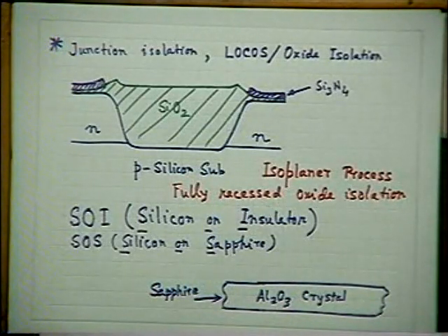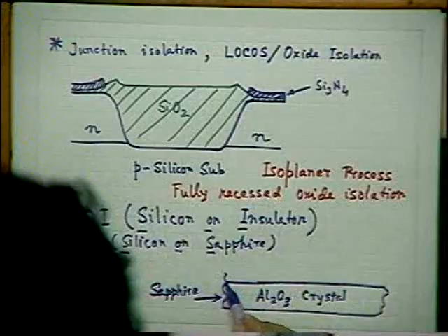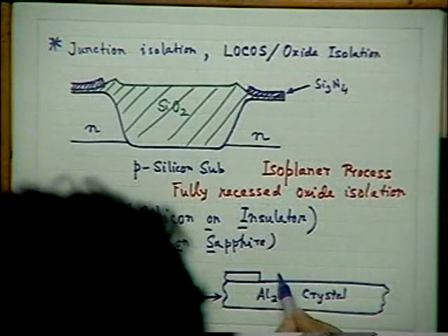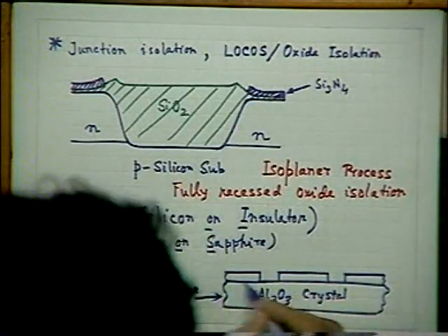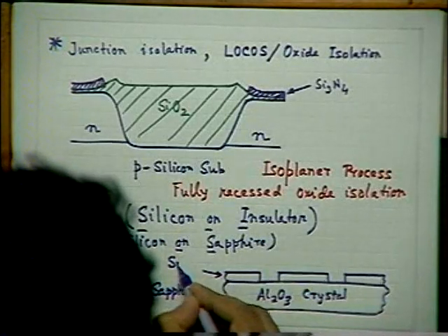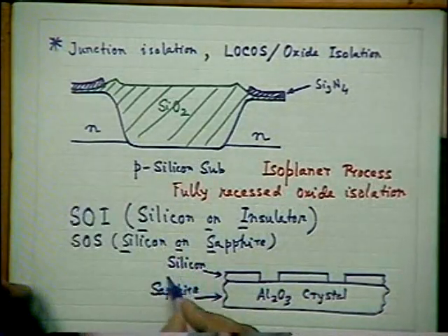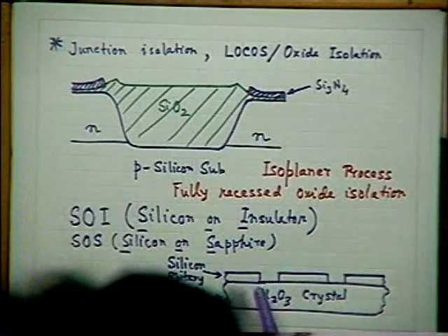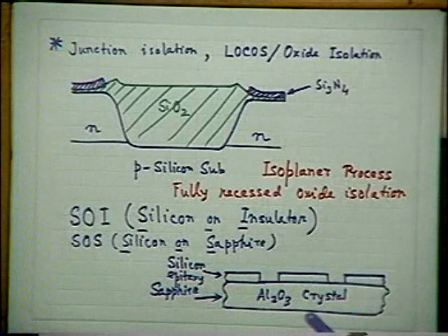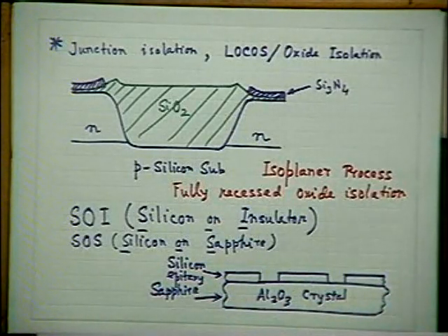And this silicon film can now be photolithographically separated into small blocks or islands, something like this. This is silicon, the silicon epitaxial film. By epitaxy, I mean a crystalline film properly ordered without any lattice discontinuity. From alumina to silicon, the lattice matching is still there, and it is a silicon film, and it can be doped or undoped according to you.